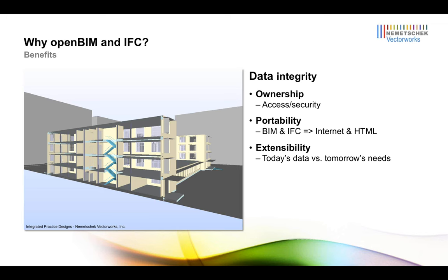Because the IFC, yes, it strips out all of those parametrics, but there is a way, and we'll see that in the future, for IFC to communicate those important parametrics in a way that the receiving application can then reconstitute a parametric object if needed in their own native format. The problem with that, of course, is doing things like tracking.